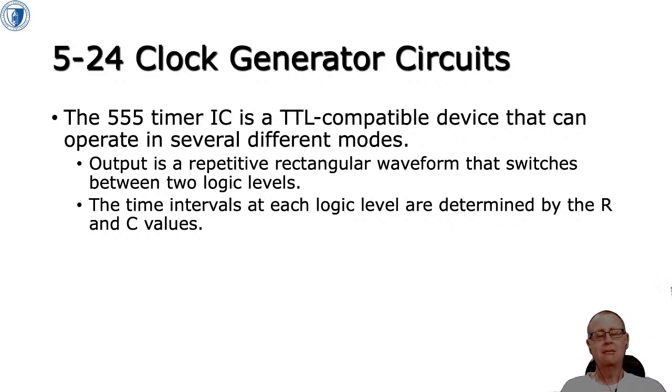There is a nice little integrated circuit called a 555 timer, and it's nice because it lets you turn the analog waveforms directly into TTL compatible outputs, and for certain values of resistor and capacitor you can generate pretty accurate clocks.